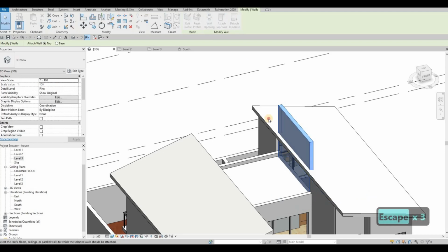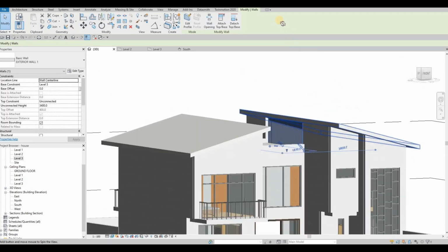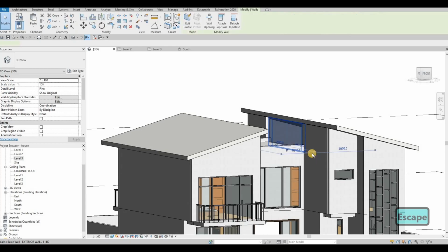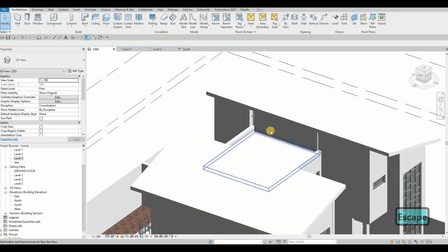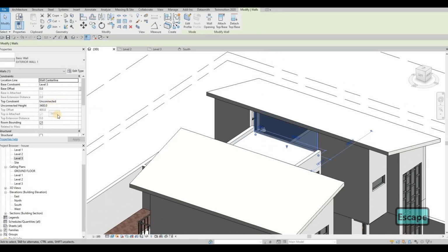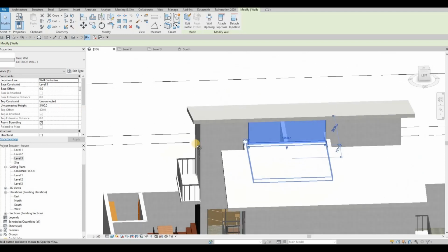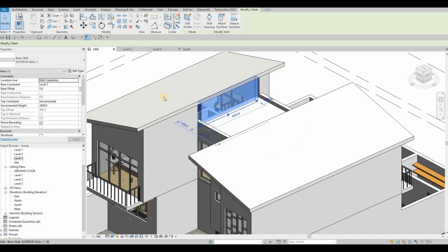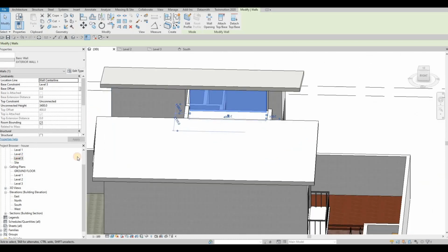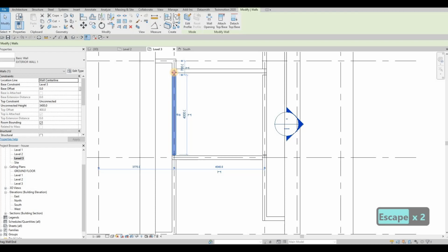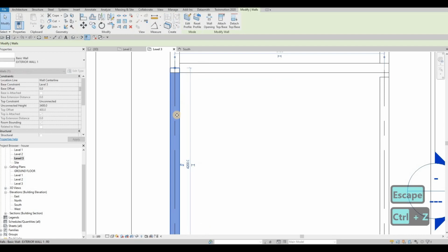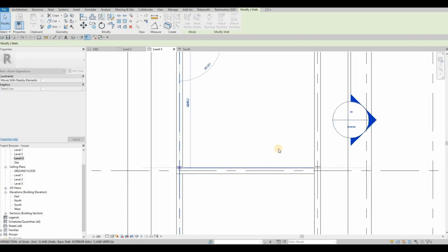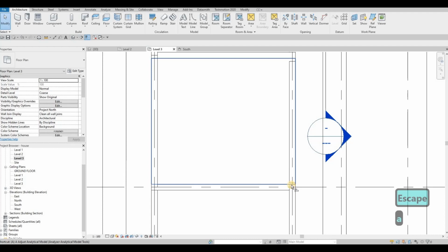Select the wall and then attach it. And then right now, as you can see, this one looks good. What it did is it basically set the base offset to level 3, and that's correct, and we can actually just connect it now. So I'm gonna connect it like that, and then right here you can align it if you want,